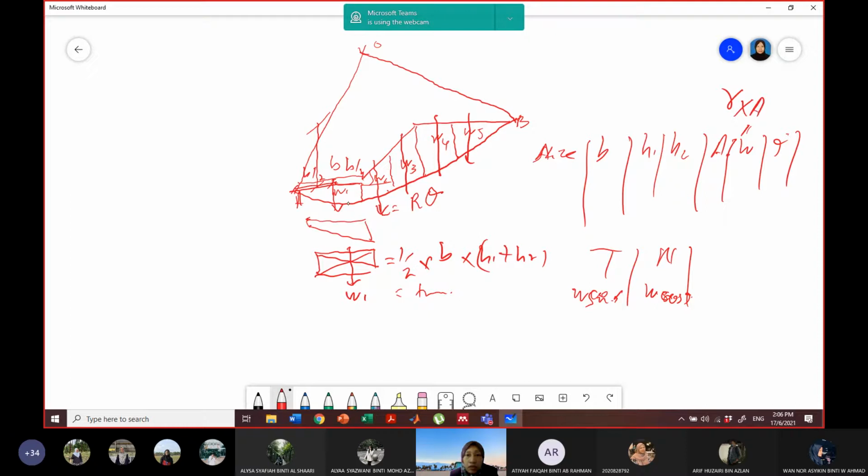And the next one is the alpha. Where is the alpha? Alpha is the interslice angle from the O to the W at the base of the slice here. So consider from O and then you point to the W position here. So if this is your W, then we can have the alpha. Remember again how to find this alpha. You need to use your protractor so that you get the angle for this alpha 1 and then alpha 2, alpha 3 until the last alpha 5.